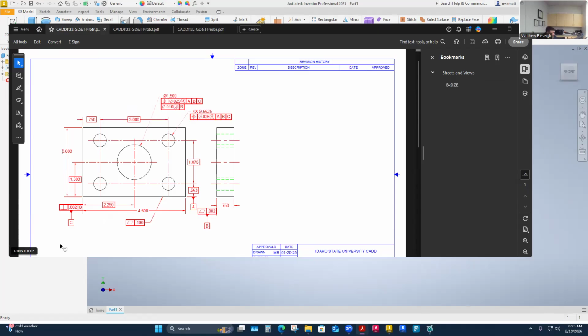Maybe we're asking a lot of a machinist there, and so maybe it'd be close. Maybe those would be better if they're like 10 thousandths, if I think of these as kind of general parts and not that I know how highly accurate of a part they are. So I want to keep this as just a general part. I think this gives you a little bit of a misunderstanding that this is a really tight tolerance on flatness. I think we could open that up if we were going to use that. I'm just going to drop those on this.